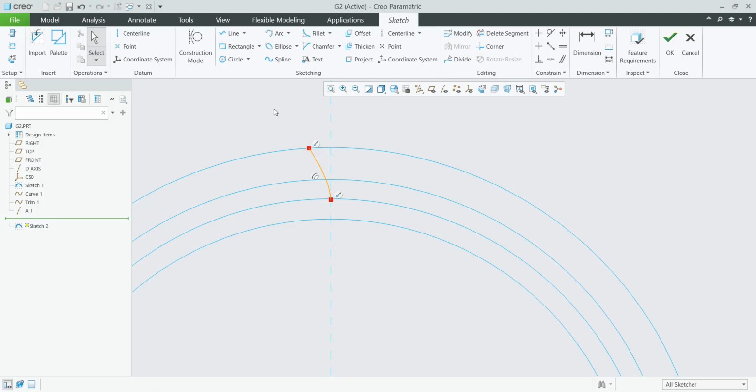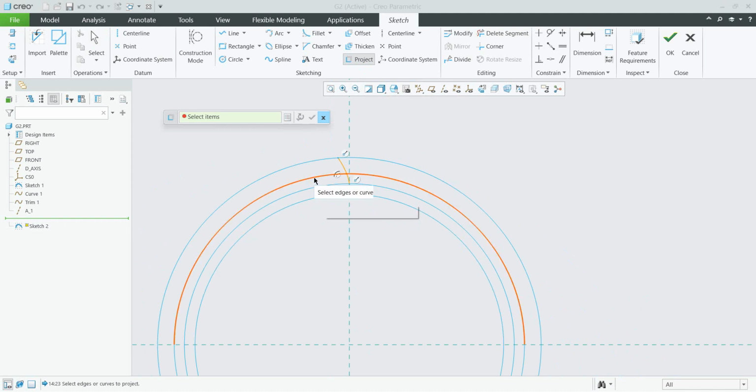During the specification of the tooth, what you have to specify is the tooth thickness on the pitch diameter. So what does it mean? Over here we have to specify the thickness of the tooth. How can I do it? I like to do it in a simple way, and we would also like to project this existing curve, but as before, I don't want to select only part of the curve, I like to use the full one. So I will select with the right mouse button and left for confirmation, and then I will confirm create geometry and close tab.